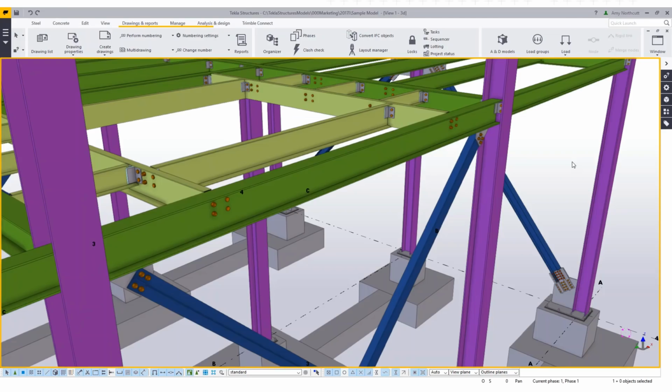And so if I show you an example of a Tekla Structures model, this is using our Tekla Structures default settings for the engineering segment, you can see some consistency among the colors here. Since our typical representation of the Tekla Structures model is by class, so I'm colorizing these members by class, the class becomes pretty important in how I visualize this model. And so you can see that all of my beams in this model are dark green. All of my channels are light green, all of my columns are purple, and all of my braces are blue, and then all of my concrete is gray. So that's one to take note of. All of my concrete, despite what member, is gray.